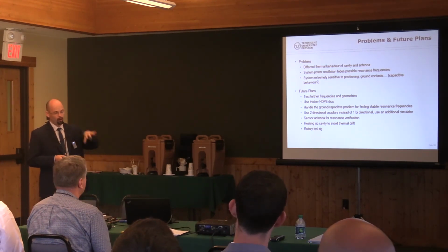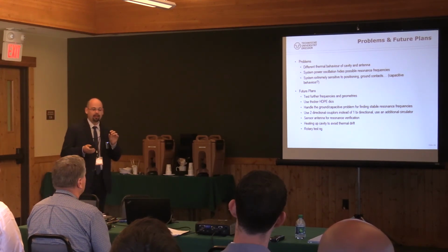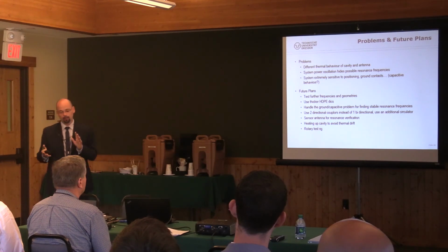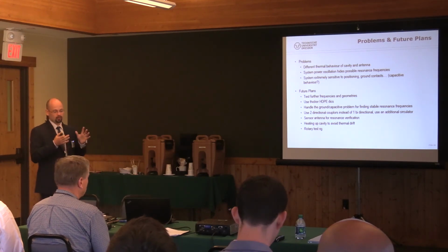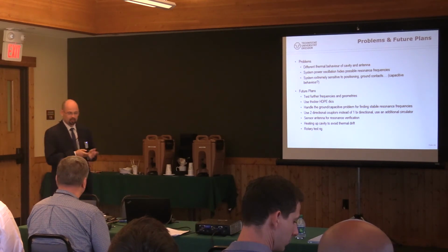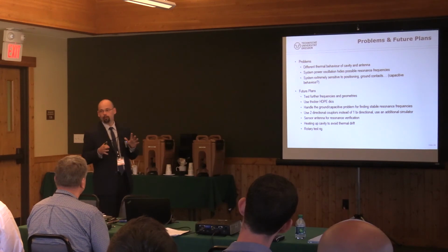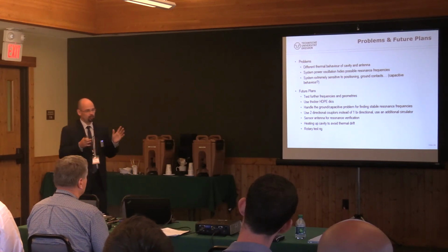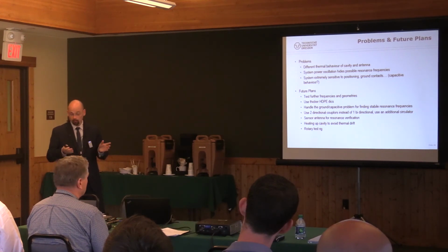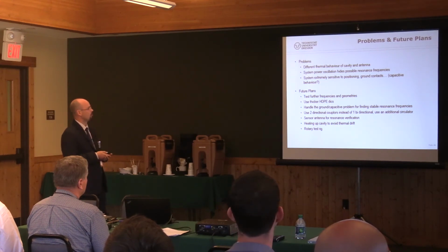So, if we power our cavity, our loop antenna expands due to thermal heating, and it changes its resonance frequency, but at this moment, the cavity will not see this kind of power and will expand in another way than the antenna does. So the matching between the emitting antenna and a resonant cavity will not be the same. So we've got some problem with matching, which could be observed further.